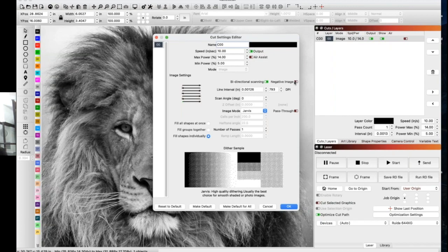I think that works better on diodes than it does for us on a CO2. Now I want to try it on Odin. That's one reason I like these RF machines. I bet this RF machine will knock it out, because you can change the frequency on the RF tube and that might affect it. And it's a 30 watt, so I can dial down to a couple of watts if I want to, or kick it up and go to 2,000 millimeters per second. It'll probably be about as good as any 7-watt laser, and I can only imagine the DPI you can pull out of that too.